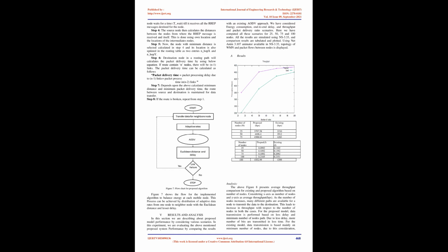Here, M users are considered for transmission. User M requires an information message of bits and is the total bandwidth assigned to the user. Constraints of EQ. 5 guarantee that the power allocated to all users at each time interval is below the ceiling value. Constraints of EQ. 6 guarantee that the information message will be delivered to each user within the predefined time horizon of t seconds, and EQ. 7 limits the bandwidth assigned per user at each time slot to the system bandwidth.